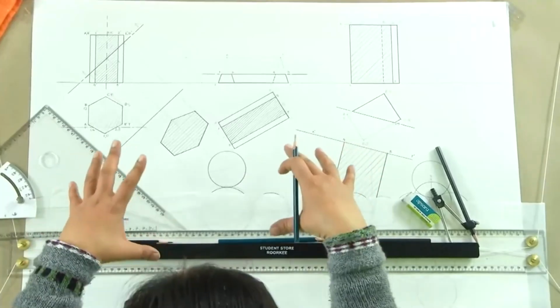With this I have explained to you the 4 cases of how prisms can be cut by a plane: perpendicular to HP and parallel to VP, parallel to HP and perpendicular to VP, inclined to VP and perpendicular to HP, and inclined to HP and perpendicular to VP. In these 4 different given conditions, we have seen how to draw the sections of the prisms.